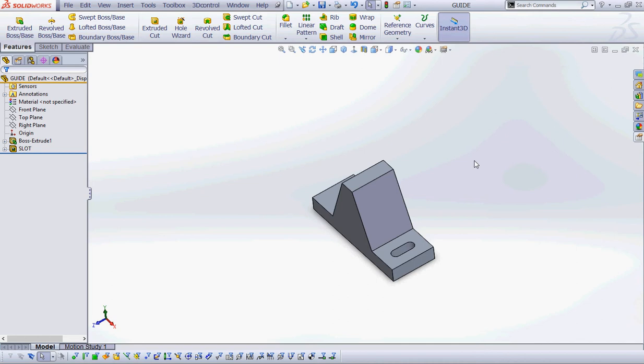A big error that a lot of students make is that they have add dimensions enabled, but they aren't paying attention that this is a diameter dimension, and in the book she gives you a radius dimension. So if the radius is 3, what would the diameter be? 6. So I'm going to say 6. And then this dimension here is 10.